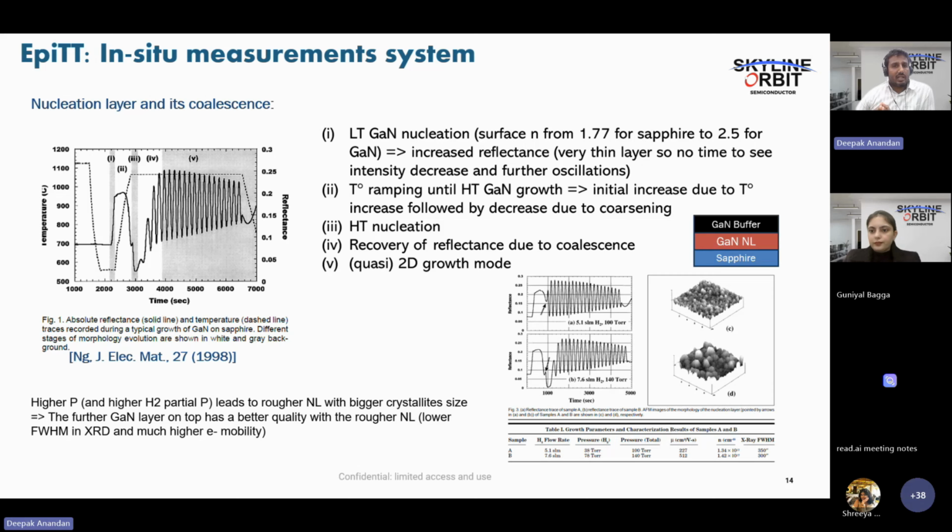So the gate reliability still remains questionable, because for the Schottky contact, they always go with nickel. Whenever you are going for the Schottky contact, there will always be a large leakage current because of tunneling of carriers, and the carriers will be injected and diffuse towards the drift region.